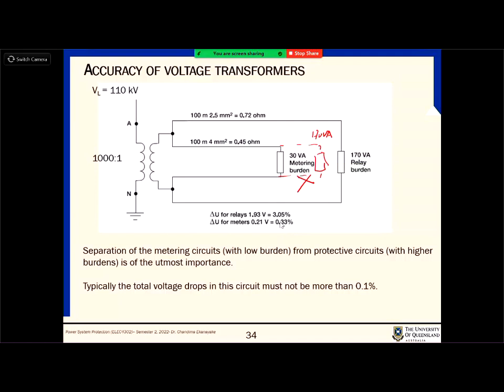And then if you are using that sort of voltage drop for metering purposes, then that affects your revenues, right? But for the protection part, even a 3% difference you can survive with, right? Because anyway the voltage changes will be very large, or the current changes will be large, and the protection is just to detect abnormal conditions, not for identifying the cost associated with energy dispatch, right?